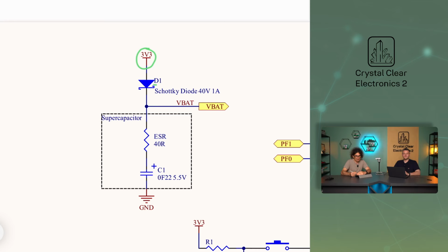To counteract this, a diode must be inserted which allows current to flow in only one direction, so that when the main power line is live, the VBAT is powered through the diode and the capacitor is charging, but if the main power supply is lost, the electrical charge stored in the capacitor supplies the VBAT input, and the diode prevents this charge from rapidly dissipating through the main power line. The chosen 0.22 farad capacitor can power the clock for a few days.